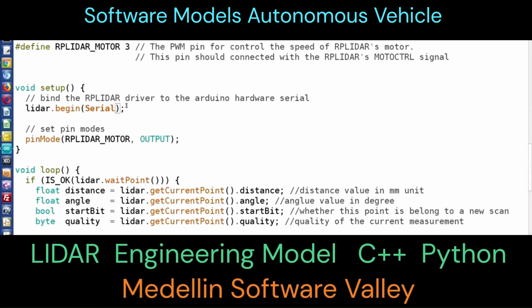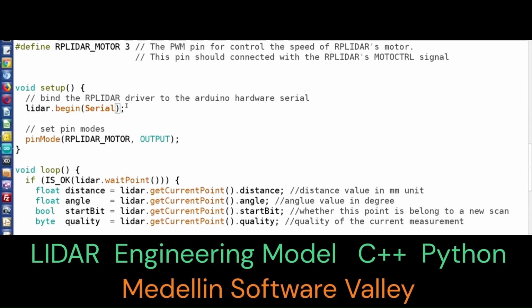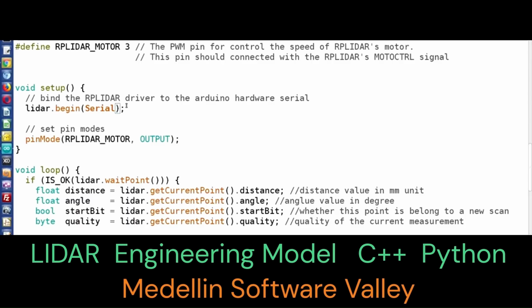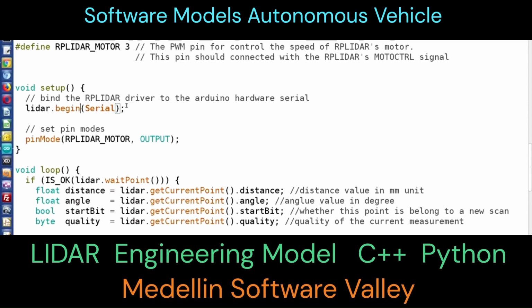In the software script, now let's set up the void loop. Take the LIDAR distance measurement. Display the LIDAR measurement, such as distance and signal strength. Now wait some time before the next measurement.